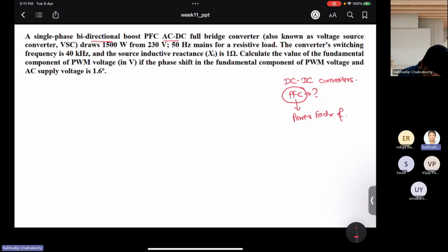No, the power factor of the supply we are talking about, right? Because the load will never have unity power factor, right? And loads may also be of DC nature, so there the power factor does not have any implication. If the loads are of DC nature, then you cannot say that it is not unity power factor or something like that, because DC loads will only consume active power, right? Clear? Yes, sir.